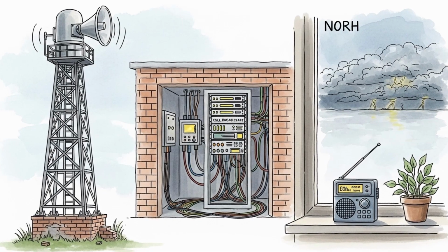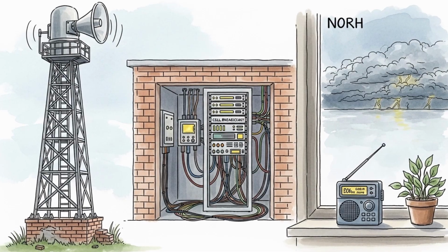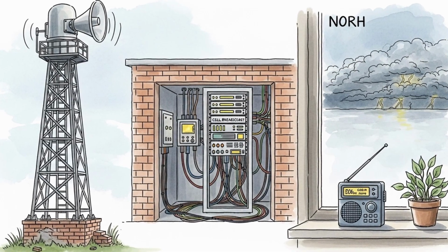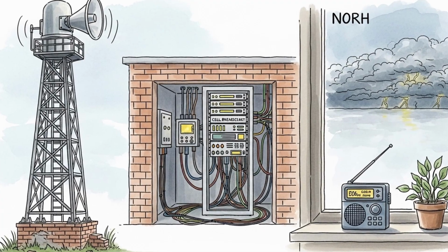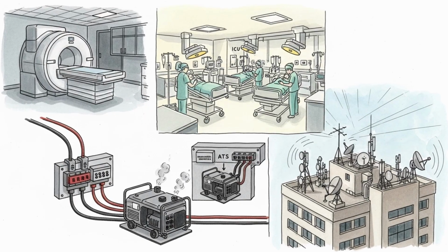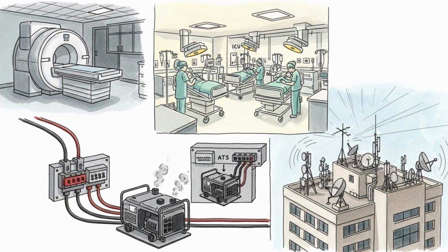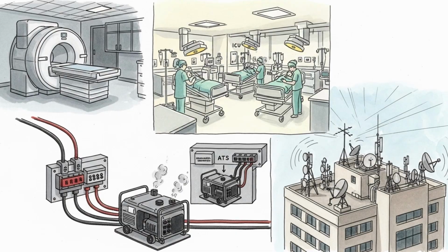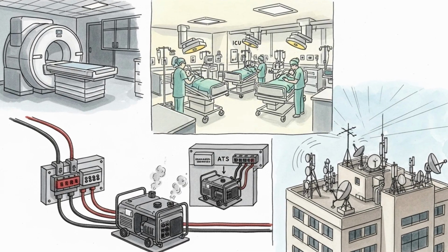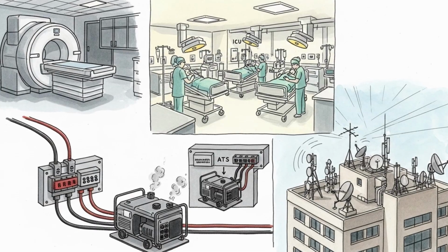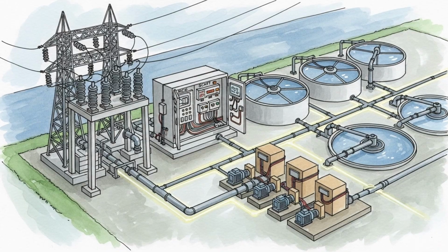Without reserves, voltage sags and protection trips can spread. Transformer design influences sensitivity. Three-phase core form units, shell form units, and banks of single-phase units behave differently. Autotransformers have direct electrical links between high and low voltage windings, which can pass more bias. Y-grounded connections provide a path for neutral current. Delta connections can block some harmonic components but do not remove the bias effect in the core.